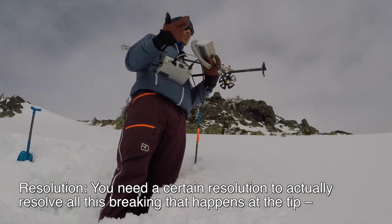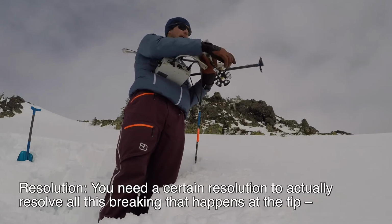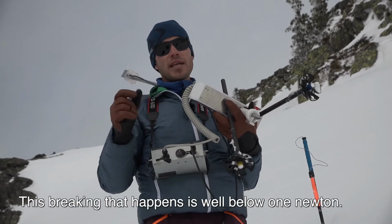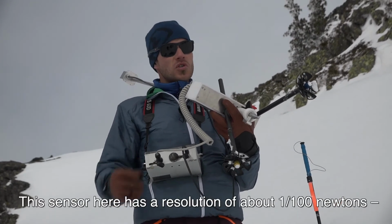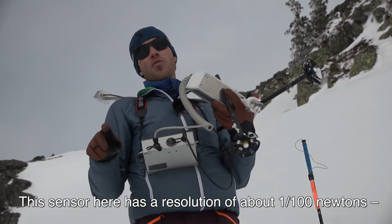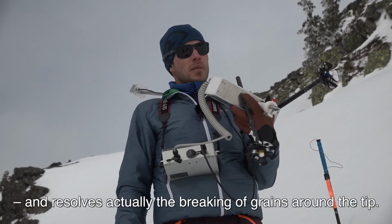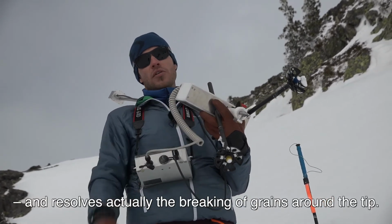You need a certain resolution to actually resolve all this breaking that happens at the tip when the cone is driven into the snowpack. And this breaking that happens is well below 1 Newton. So this sensor here has a resolution of about 1/100 Newton, so 0.01, 0.02 Newton, and resolves actually the breaking of grains around the tip.